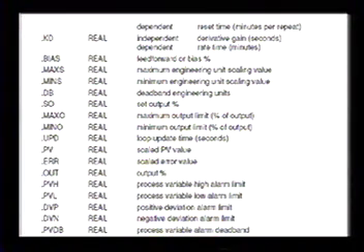And you can say, okay, I don't want the control variable to ever open up more than 90%, because I know when I'm at 100%, I can't control this thing anyway. So I don't want that condition to happen. So I limit it to 90%. And I don't ever want that control valve to close all the way, because if I do that, then I'm going to deadhead the pump and destroy the pump. So we don't want that to happen. So you set max O to 90% and min O to 10%. And then no matter what your controller tells it to do, it's going to be within that range.